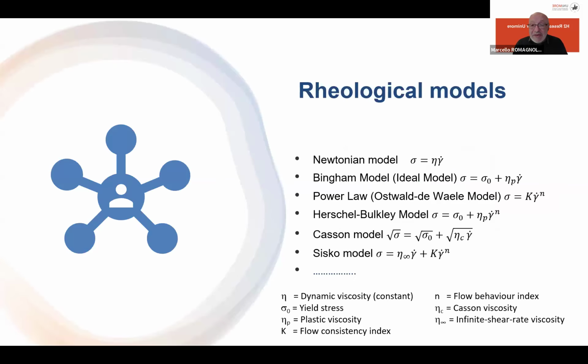So we have several rheological models for when the material flows. For example, the Newtonian one is the simplest and is great for water or slip suspensions with a low amount of solid content, but not for the ones generally used in ceramic production, both traditional and advanced. If we use the Bingham model, a bit more complex, we introduce the yield stress concept here.